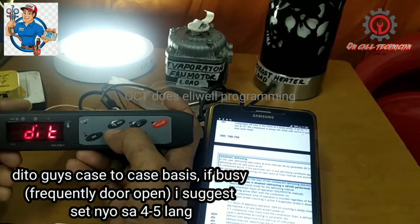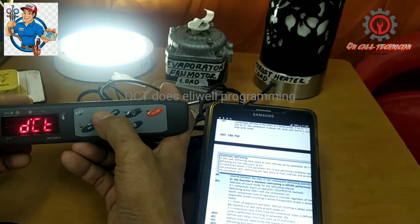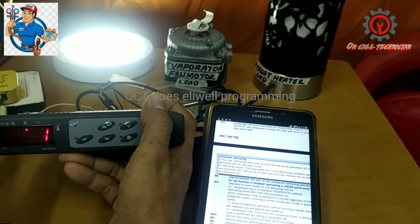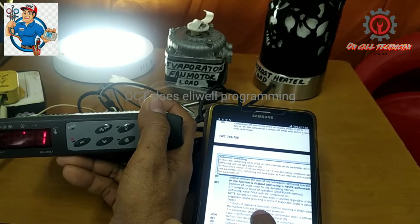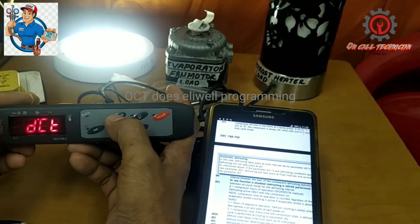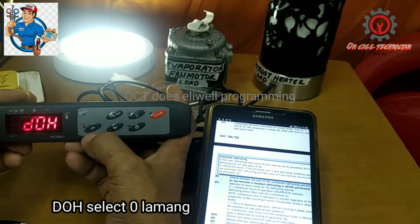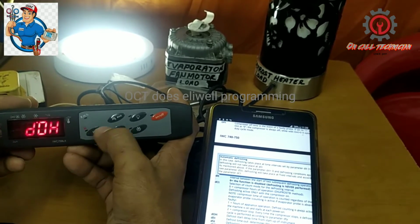Okay, so just press set button and let's proceed to DCT. Now the DCT, guys, is the DCT counting mode for the defrosting interval set. Now we're going to select the 1, which is the hour of appliance operation. Okay, then let's proceed to DOH. Defrost start delay time from start of the instrument, so we don't need to delay the defrost. The value there is 0, so no need to change that one.